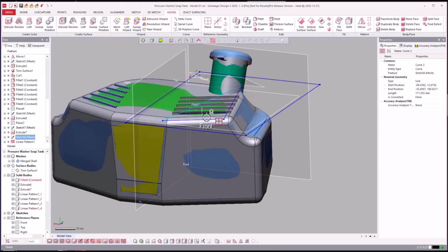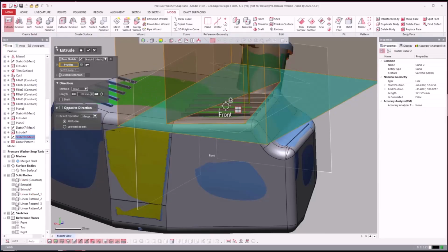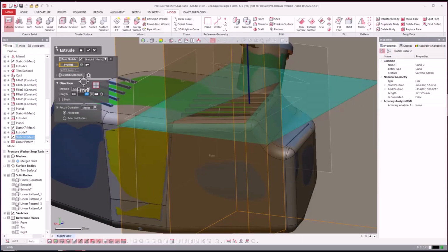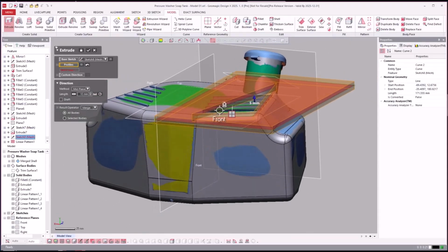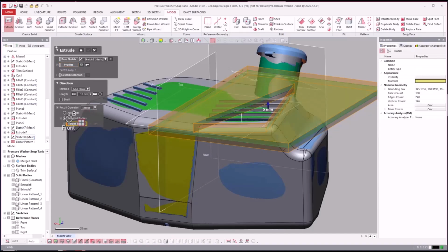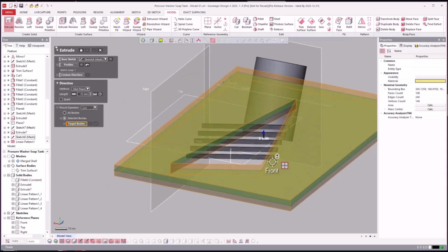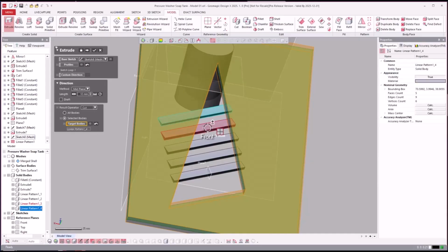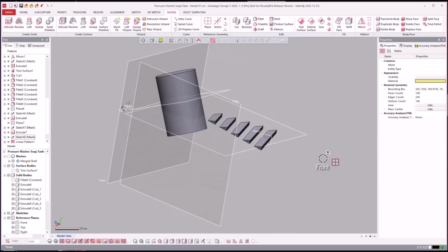And then I could have not put this boundary around there. I could have just extruded this and done the difference. But something about the way DX does the difference is a little bit different than some of the other softwares out there. And it was just easier for me to draw an outer boundary around this. And I can say cut selected bodies. So just hide my mesh, hide this guy, and I can say cut all these. I could do this in 2 steps with booleans, but you understand.